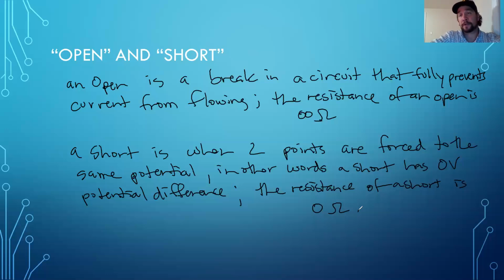There's less to oppose the electrons, so the current goes up. So when we do our measurements and we notice that the current is actually larger than our expected current, then we can suspect that either we made a mistake in our calculation, or maybe one or two of our resistors are shorted out. All right. So let's look at a couple of examples.